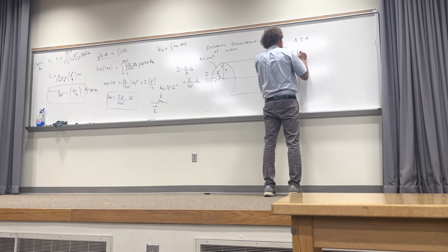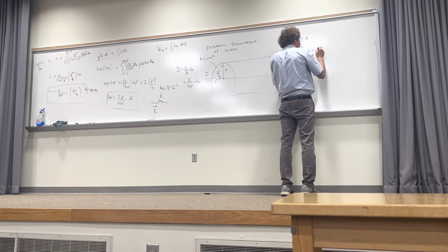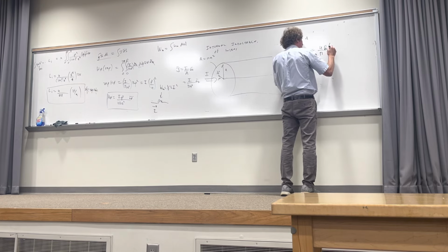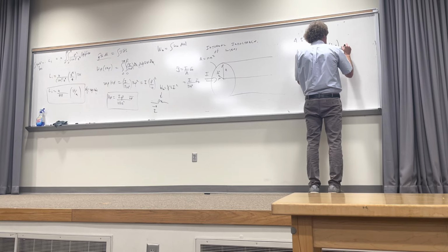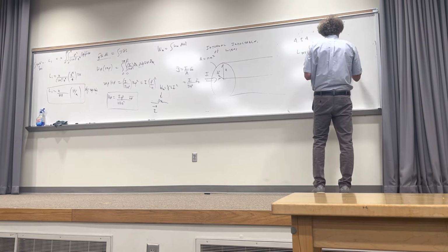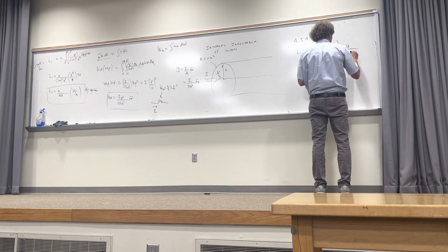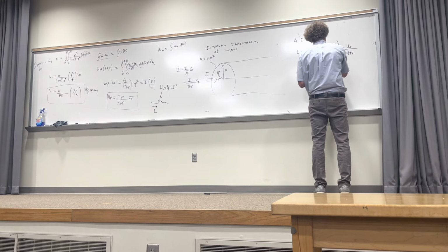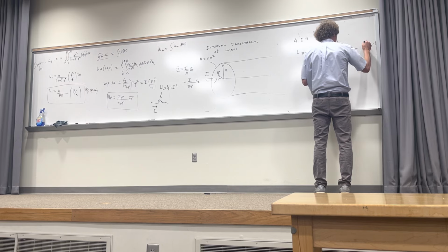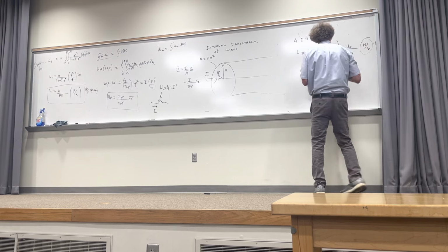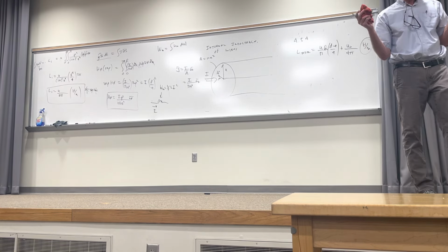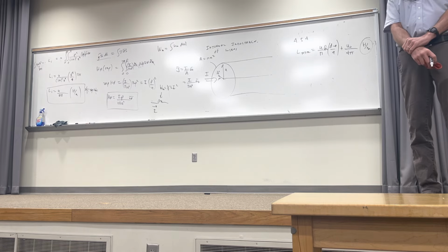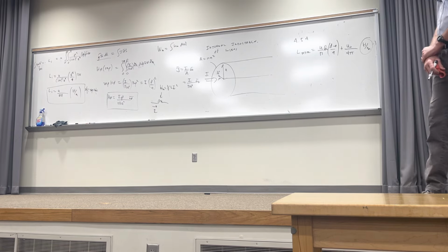Now, the total inductance, this is going to be total, was equal to that mu over pi times natural log of B minus A over A. This is per meter plus twice that, right? So it's really going to be plus mu over 4 pi. And this is going to be mu 0 if it's non-magnetic. And that's going to be in henries per meter. And that would include the internal inductance and the inductance caused by the flux that's actually between the wires. Do y'all follow me on this? Is that the answer, by the way, that he gives? You go ahead and write it down, but.